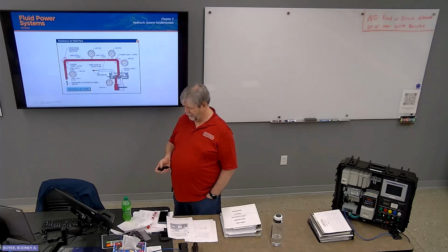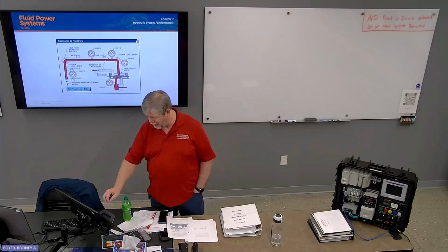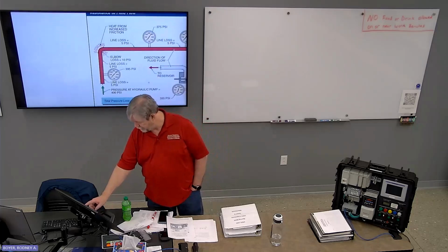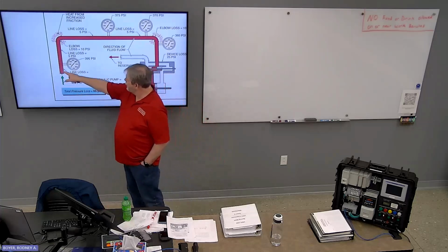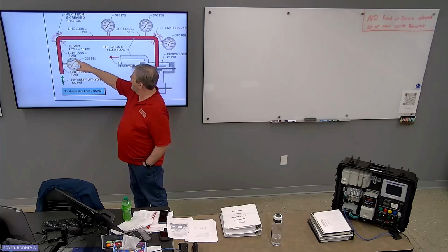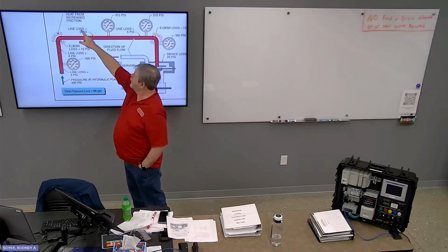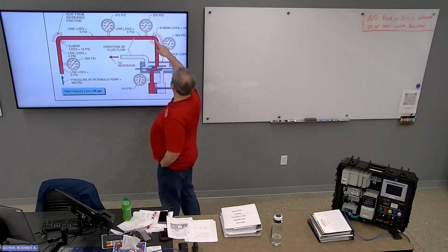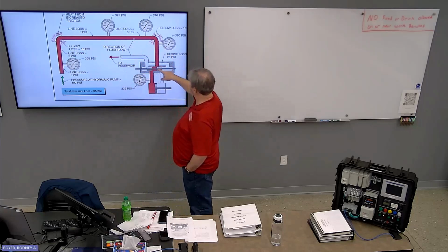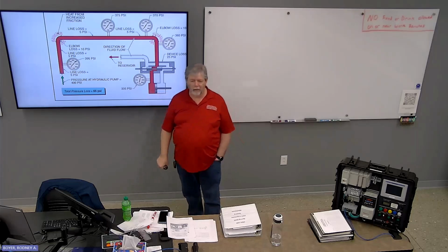Resistance to flow. System starts at 395 psi, or no, 400, I guess. But you've got 5 pound line loss. You get down to 395, and then another 5 pounds of loss there, 10 pounds going around the corner, which turns into heat. Another line loss of 5 pounds, another line loss of 5 pounds, 10 pounds going around the corner, 25 pounds lost through the device. So by the time you get down here to the piston, you start with 400 pounds and end up at only 335.